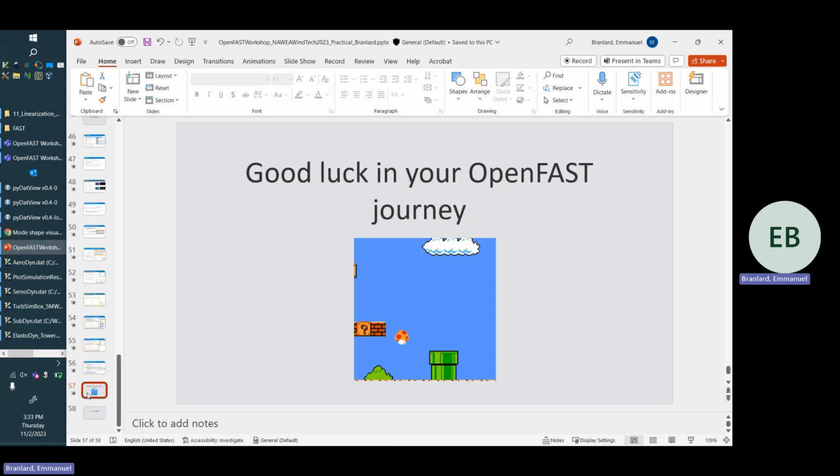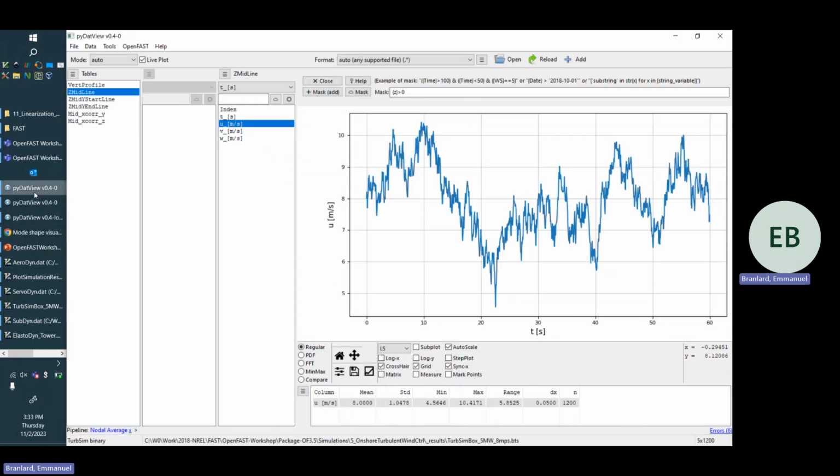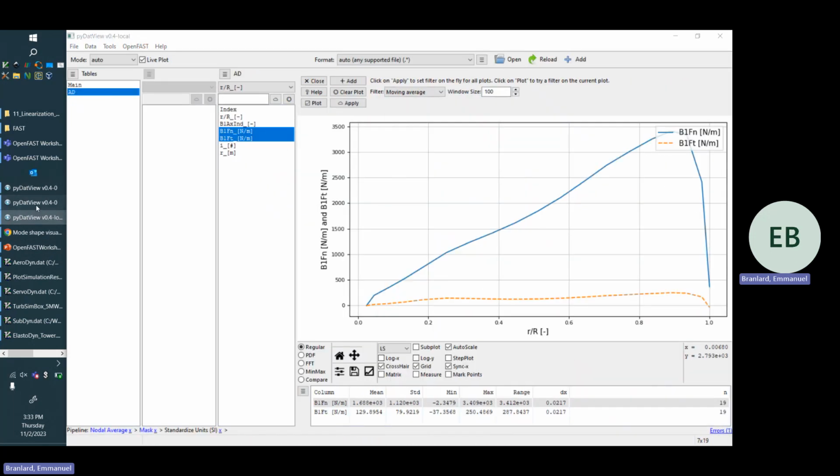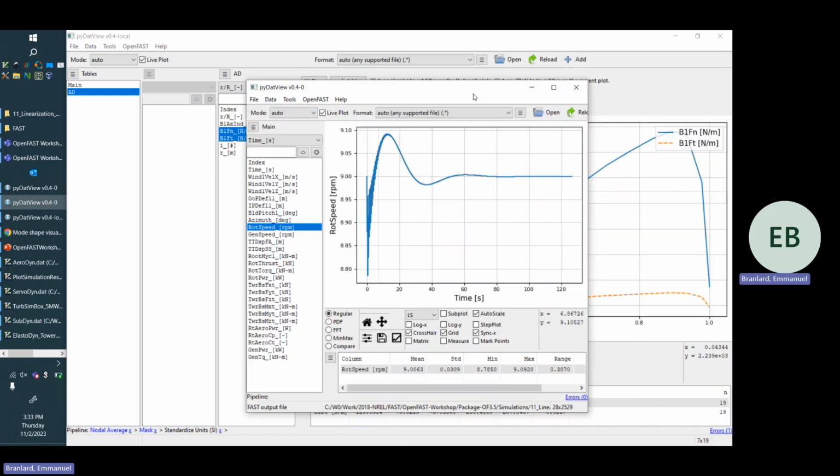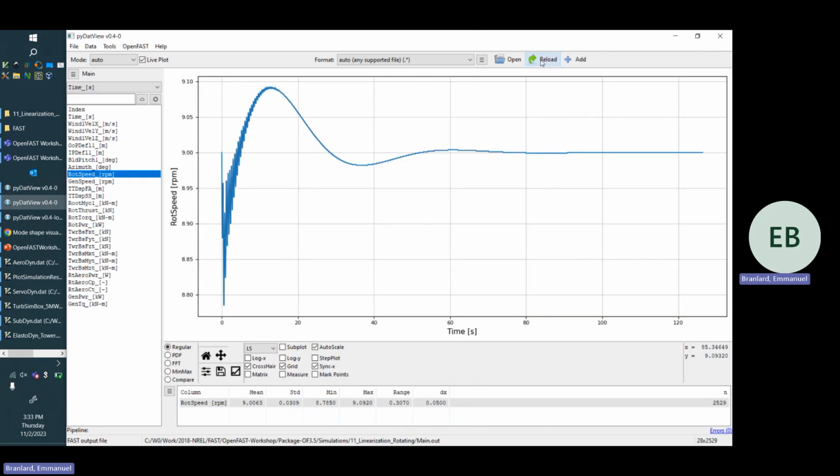Got one question. If I specify the simulation to run for 100 seconds, but use the calc steady option, it terminates when it finds steady state. It doesn't run any further. That was this case I ran as well. It was probably for 500 seconds or 400, and you're right. It stopped at 120 seconds.